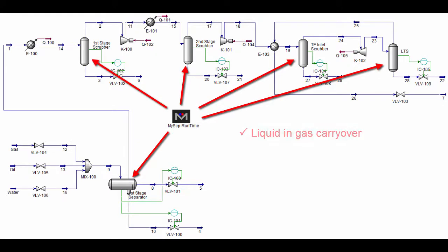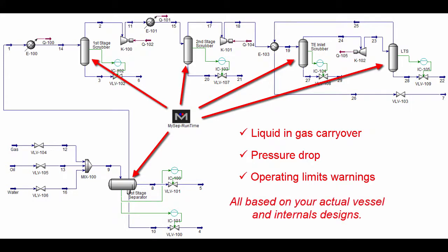It calculates liquid and gas carryover, pressure drop, and also provides warnings when the operating conditions exceed the capabilities of the vessel and internals design. All the calculations are done based on the actual vessel design geometries that you import from file.